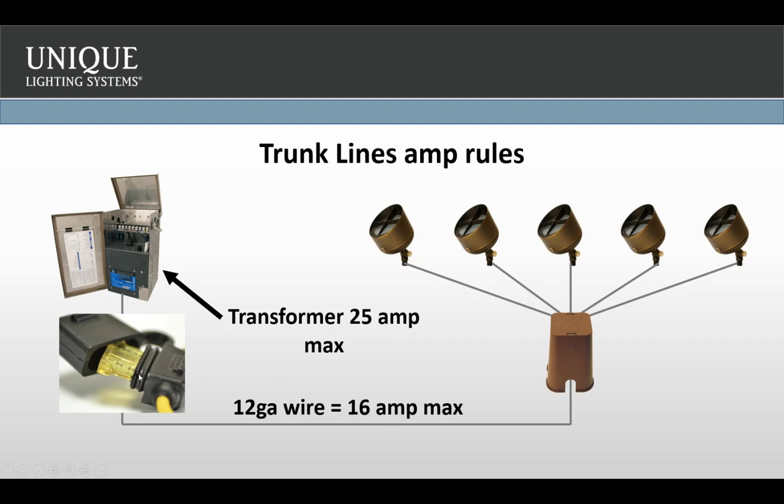So to save that, this is where we put the fuse, and then we've got to size that fuse per the load. So you want to have no more than a 16 amp on the wire. If you've only got, let's say, 10 amps out here in the field, then maybe I only want to put a 10 amp fuse on that wire. That way I'm making sure that I am catching that short if it happens out in the field.